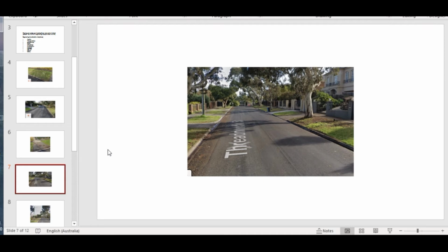Is that a material I can use for filling or cutting? Is that material worth using? Making sure at an earlier stage whether we can use the material in a good way, or we can discard the material, or we can store and use that material for building up the road. So these are the things we are involved in as a part of civil engineering too.